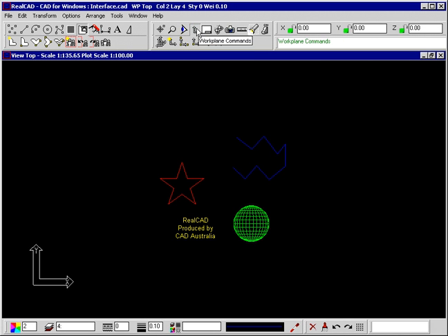To the right of the interrupt toolbar is the coordinates bar. This contains fields in which you can enter distances, angles or coordinates from the keyboard as input to commands. You can also lock distances and angles to assist in inserting and editing the entities by clicking on the padlock symbols. Green is unlocked, red is locked.